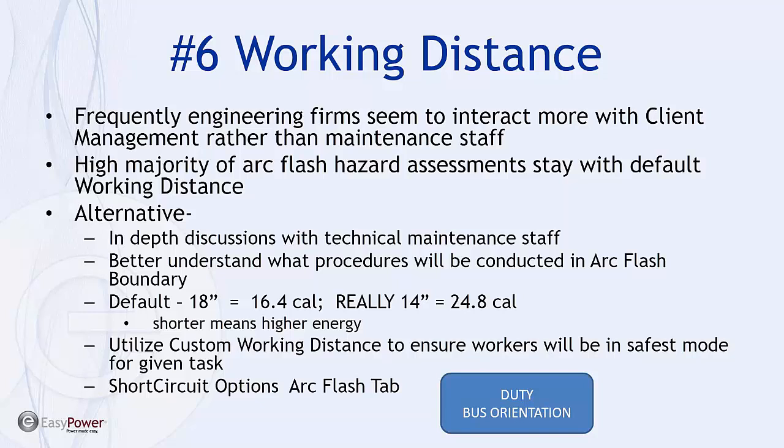If I'm poking my head in the only opening, I have to look with my face inside a box as I'm making adjustments or taking readings, and that's the only area that energy can escape from this enclosure, and my face is supposed to be farther away than the default distance. The fact is I will be exposed to considerably more energy because at that point, an important part of my body is not at arm's length away.